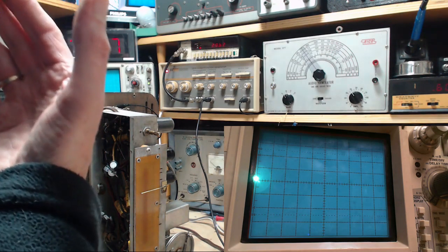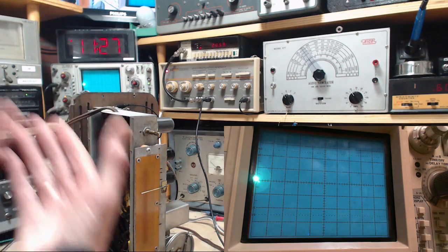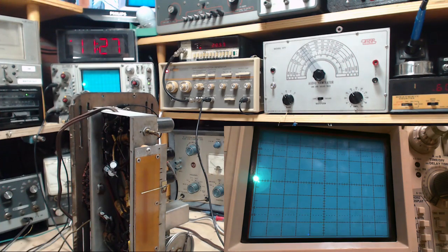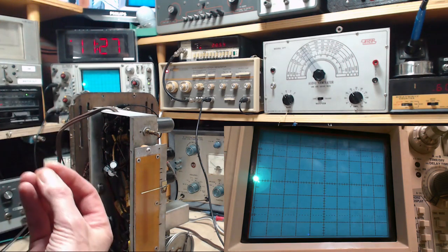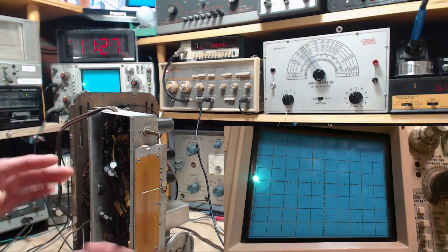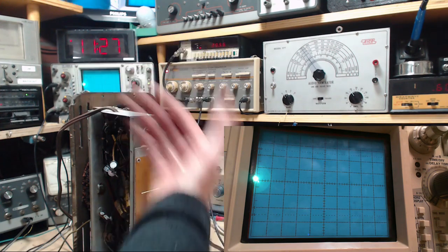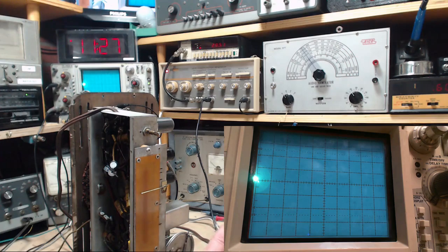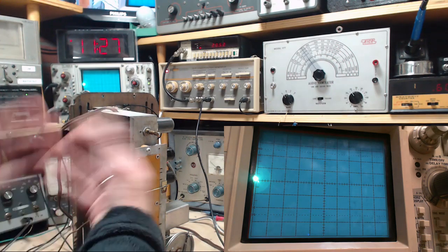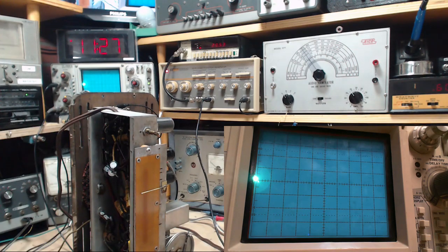Because you're using the local oscillator to do a frequency conversion, it can't be. If there is something sitting there, it can't be in the front end of the radio. It would have to be further on in the radio. And we are examining the output of the IF at this point. Could be in the IF. What would that be? That'd be like a secret little resonance point.